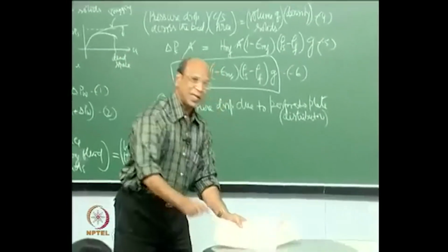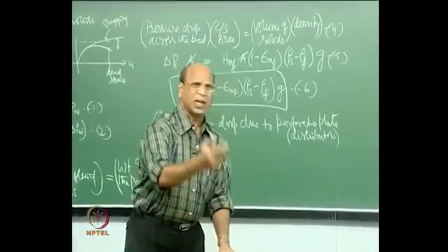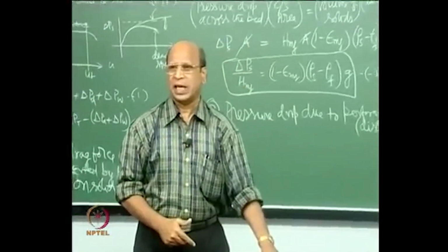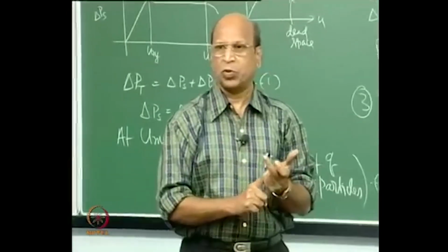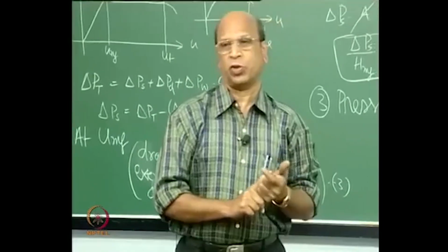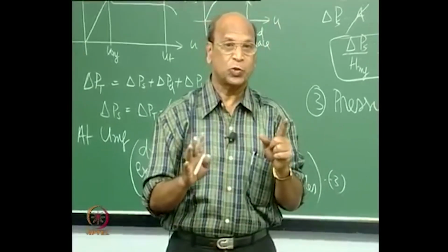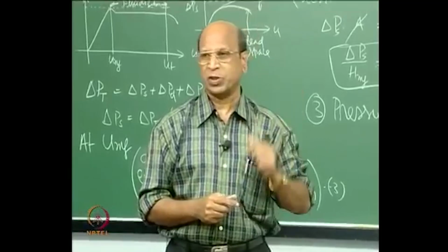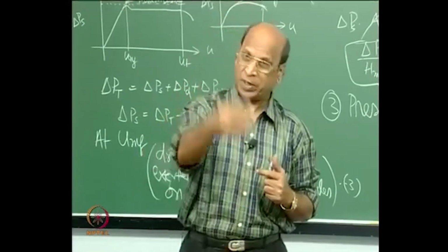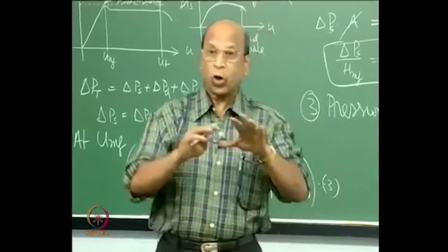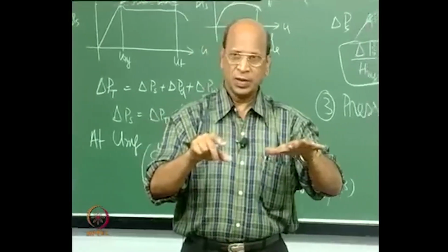Okay. So, that is why the general thumb rule is, of course, there are many thumb rules for distributor design. I am talking about this is one, bubble caps can be used, sieve plates can be used, and also there are porous distributors, which normally we never use for distillation or absorption. We do not use, because pressure drop will be tremendous. Okay. Porous, you have seen the porous distributors, it is like membranes.